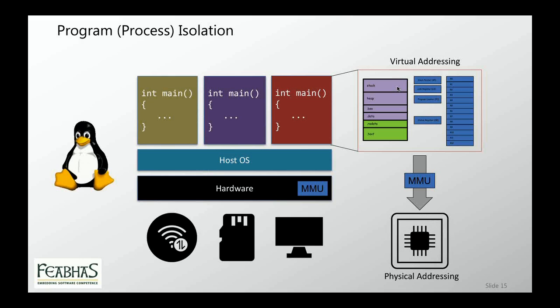So at this level, we would expect a memory management unit. A typical ARM A9 or ARM11, for example, supports the MMU, and that's required by an operating system like Linux to give us this program isolation. This is done using a virtual memory model. The application sees a linear address space, and thinks that's the physical address space, but the MMU is doing the translation to physical addressing. The benefit of this level of virtualization is that if a program crashes, it cannot bring down the other programs. So it's a first step in terms of giving us a form of isolation.